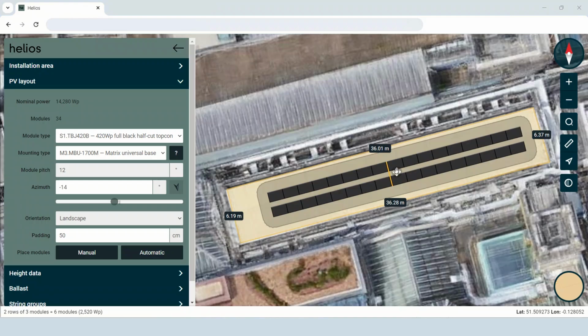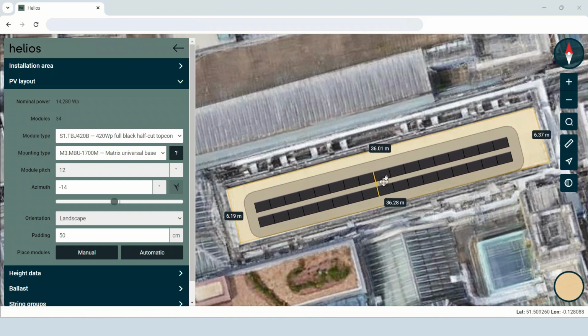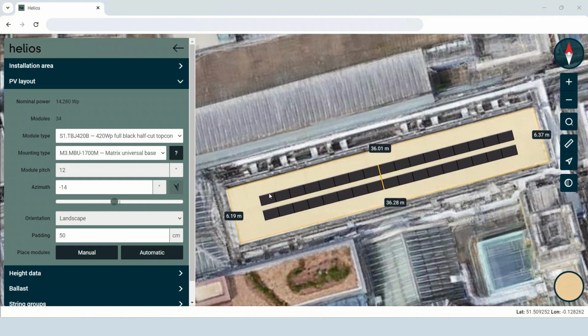Once you have created a field of panels, there are several options to customize the design. Selecting multiple panels in the field is done by holding down the right mouse button and dragging. Undo the panel selection by pressing Escape. Press the Move icon on your screen to move the entire field. Click on a panel to select it. You can then detach it from the field. Drag the field so that the gray border around it overlaps with other panels to add it back to the field. Hold Alt to prevent snapping.